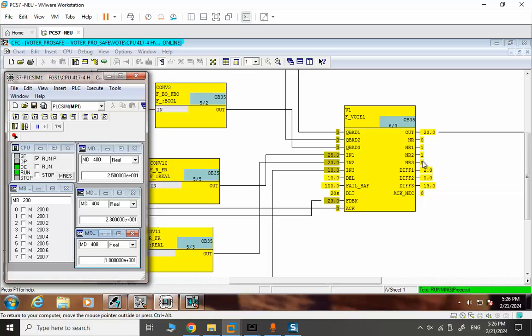But when we have two signals, like 25, I change it to 45, and for a period of time it's okay. You can see difference 1 is huge. We wait for 20 seconds. The delay time you can adjust. When we have two deviations after this delay time, the output will be fail-safe. The output will be fail-safe, and it's a shutdown. After the shutdown, possibly we check everything and solve the problem in transmitters, and we return the machine into the normal operation. And still we have that 100, and we need to reset. So the block is getting back to normal.